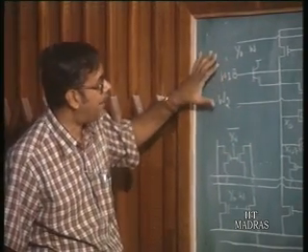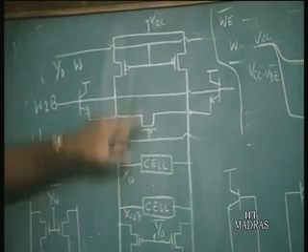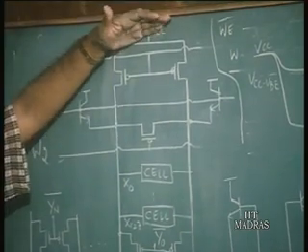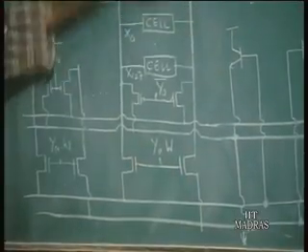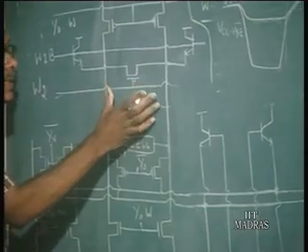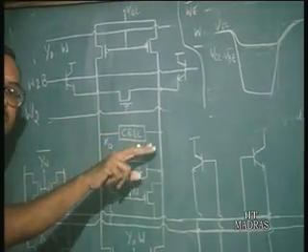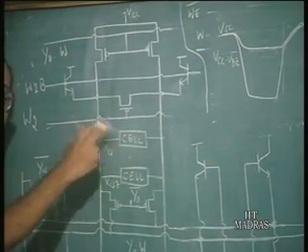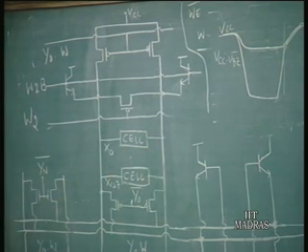So, basically you have these cells, which are 4 transistor cells. So, these are pre-charged to VCC. In this case, of course, VCC is 0 volts and VEE would be minus 4.8 or whatever. So, this cell, which is a 4 transistor cell, one of the transistors would turn on to reduce the voltage slightly, because this is a 4 transistor cell, not a 6 transistor cell. So, that creates a small difference voltage, which is basically being sensed.